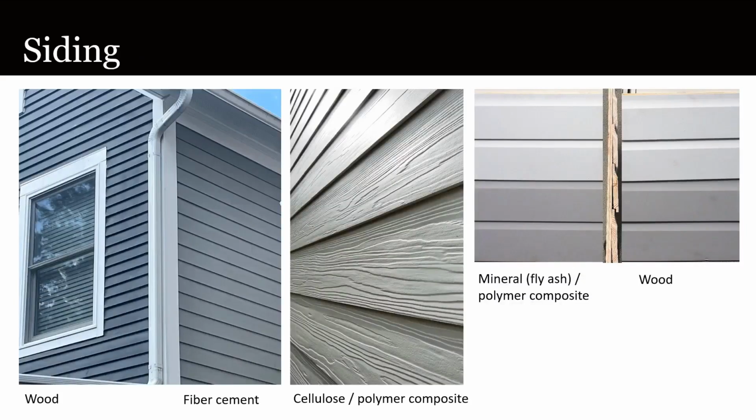For any wood frame building, siding is a major contributor to its character, and where historic wood siding is in place, any needed replacement will need to be a good visual match. Though there were a variety of profiles used, particularly in the late 19th century, basic lap siding or clapboard could be found throughout the country from the 18th through the 20th centuries. Its thickness and exposure might vary with the date and style of the building, but 4-inch exposure was fairly typical on 19th century buildings, whereas siding with a wider exposure would be more commonly found on a 20th century house, maybe in the craftsman style.